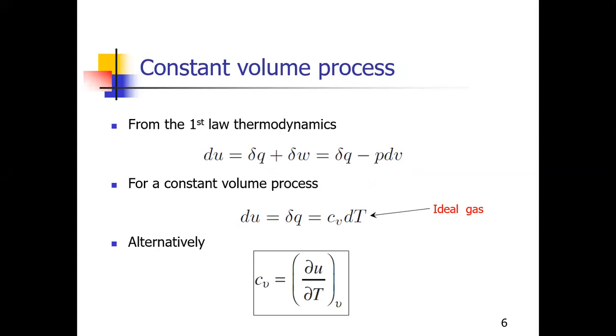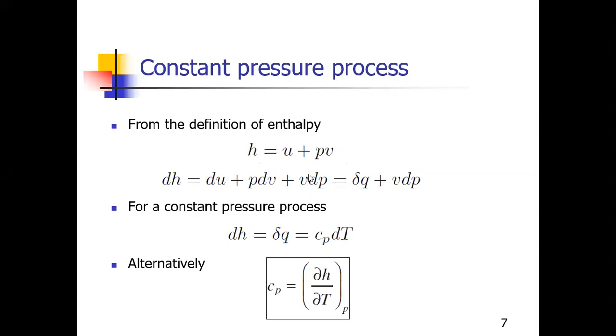If you do have any question, raise hand or speak. If you are confused, please raise hand. Because, in a constant volume process, all the energy went into internal energy. Here, not all the energy went into internal energy. Why? Because let's say the process is a constant pressure process, so this goes to 0. So any heat that you add, which changes your enthalpy, let's say 30 of it was used to do some work on the surrounding, and 70 is added to your internal energy.